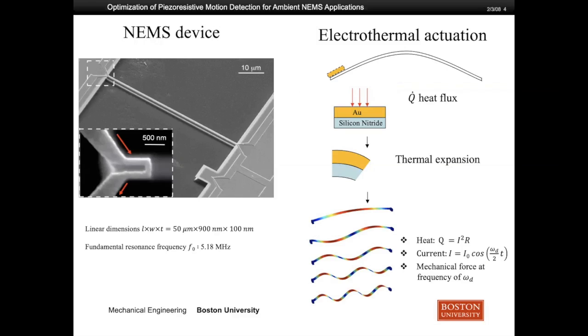First, this slide shows what device is used and how I do the actuation. The device used in this work is silicon nitride double-clamped beams under high tension. We thermally deposit a metallic thin film on both ends of the beam for actuation and detection purposes. We electrothermally actuate the beam based on the fact that the thermal expansion coefficients of the gold thin film and the silicon nitride are different. When the current passes through, the film is heated up and it bends towards the substrate.